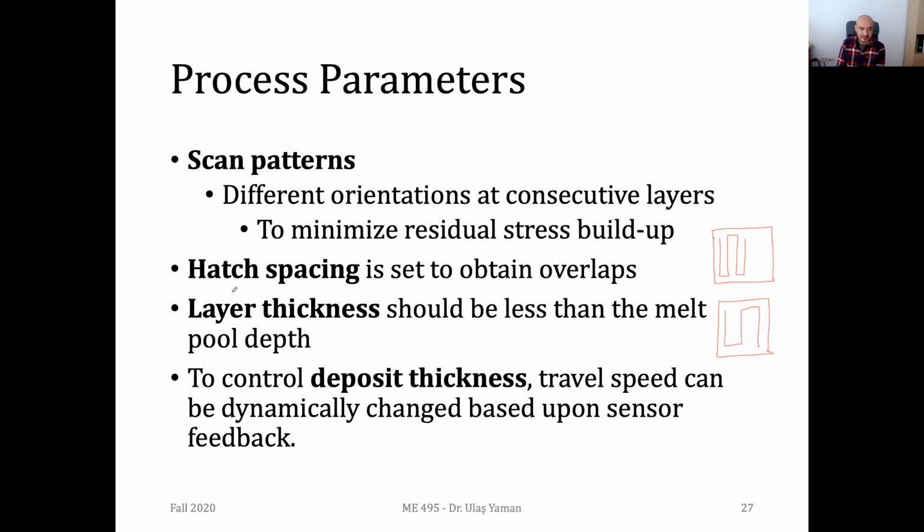But if you have, let's say, your focal point or the size of your molten pool, I'm just giving some numbers now: 2 millimeters, okay? The diameter of your molten pool is 2 millimeters. So assume that this gap is 6 millimeters, then we will have 2 millimeters, or I'm sorry, one from here, one from there. So we will have 4 millimeters of gap between the deposited material. That will be the thickness of this edge, and this is another thickness of the neighbor edge, and we will have a gap of 4 millimeters, right? If the diameter of your molten pool is always 2 millimeters. Which means that after this layer is over, you will have some regions which are not filled with material.